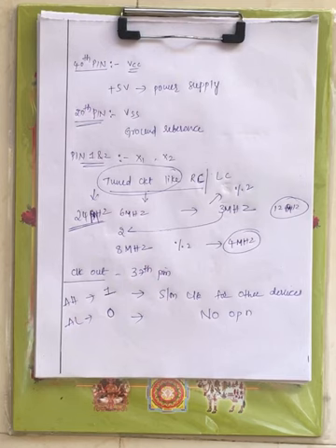We connect a tuned circuit like LC or RC or any other oscillator at these pins. It will generate some oscillator frequency, and that divided by 2 is the operating frequency of the processor. If it generates 6 megahertz, divided by 2 gives you 3 megahertz. The division by 2 is done by the internal clock generator.